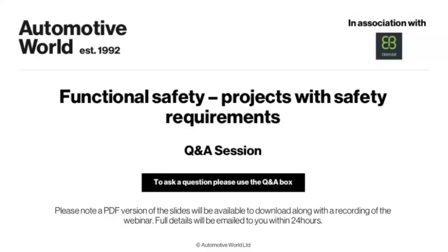But yeah, you need to find your argumentation, right? If we talk about the ASIL-B ready package, where we have technically QM software residing in the same partition as a safety system, there you need to find an argumentation. And here our argumentation is the non-interference, which means that there's no data corruption caused by the QM part to the safety part.